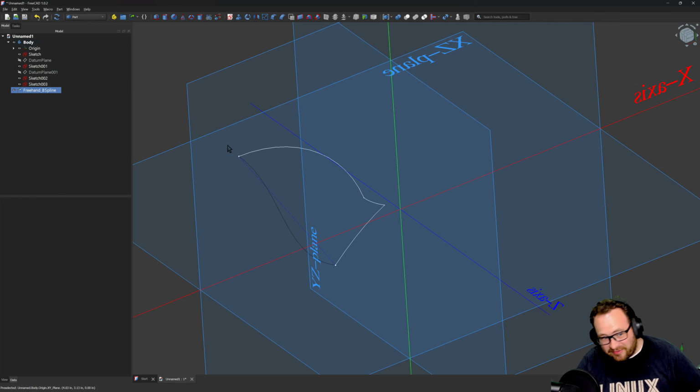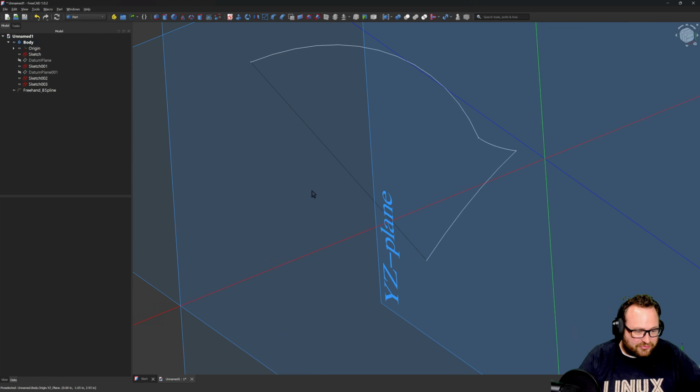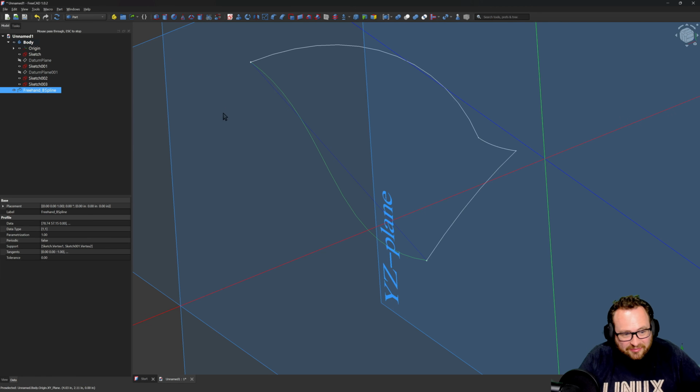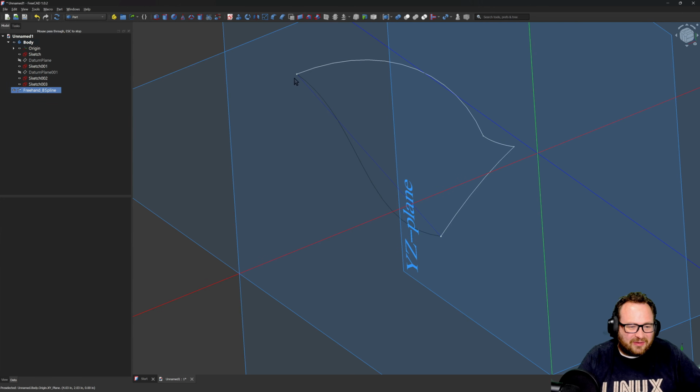Now you're going to notice something. I'm going to double click to stop editing my B-spline, and it goes straight. And we say, oh, do I have to do that view thing all over again? So if I double click, which puts my spline in edit mode so I can change things, it's curved again. And we think, what's this behavior? Why is it not the shape that I want? And the reason is the spline needs one more point.